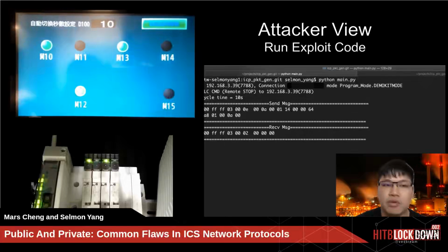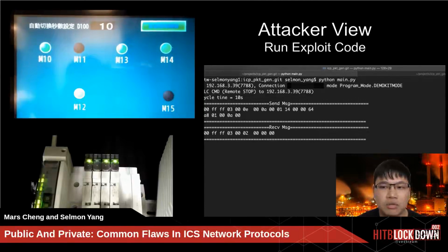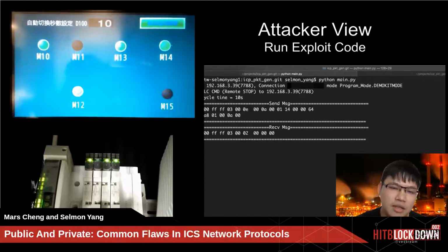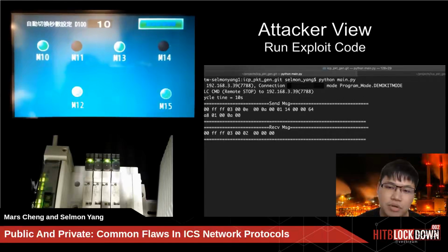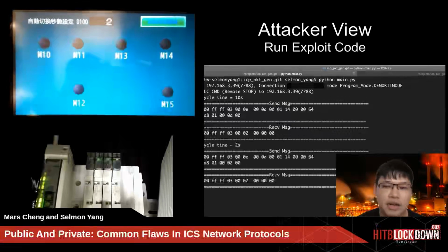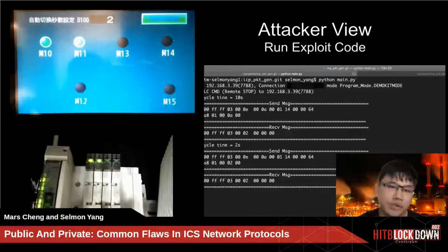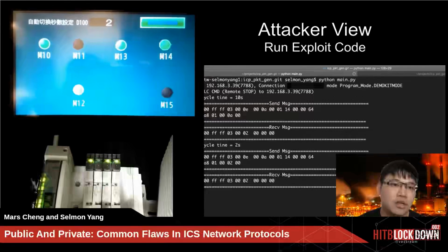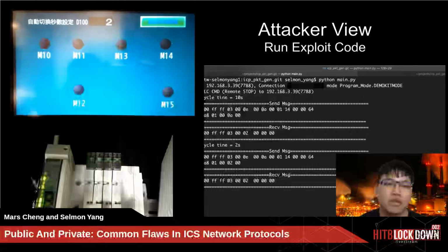In this scenario, our attack goes from 30 seconds to 10 seconds to 2 seconds to 8 seconds and back to 30 seconds. This attack demo is very similar to what a Stuxnet attack might do, because the field devices cannot withstand high-frequency switching; they suffer physical damage and cannot be used anymore. So we may simulate this demo scenario for Stuxnet.